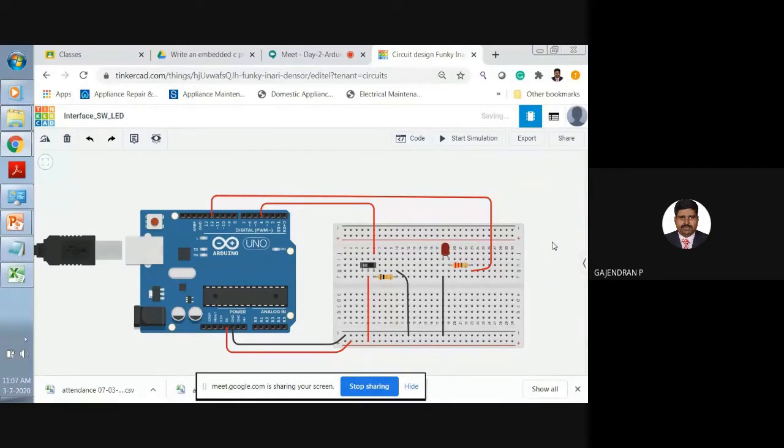That's all. The hardware connection is over. Now only the coding part. I repeat once again. Get all the components. Keep the Arduino board and breadboard and power the breadboard first. Then, your wish: if you want to connect the LED first, connect it, else if you want to connect the switch, connect it. Whenever you connect the components, please keep the cursor near the terminal. It will help you by identifying the name of the terminal.